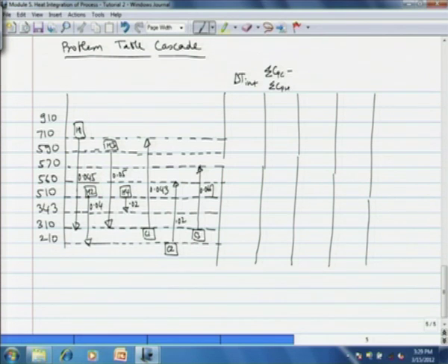And now we have to list the delta T interval, then summation Cpc minus summation Cph for that particular interval, the summation of the heat capacity flow rates for cold streams minus summation of heat capacity flow rates for hot streams, then delta H interval, then we have to find whether the interval has surplus or deficit of heat, and finally the surplus deficit after hot utility addition.